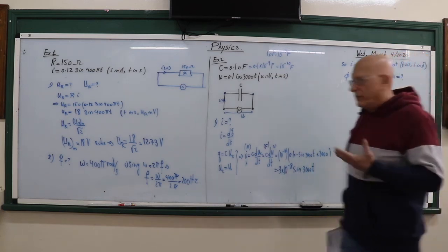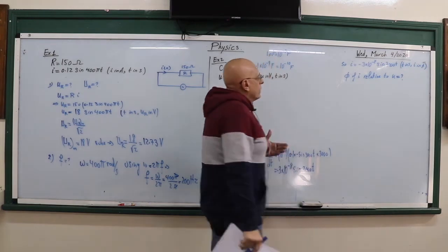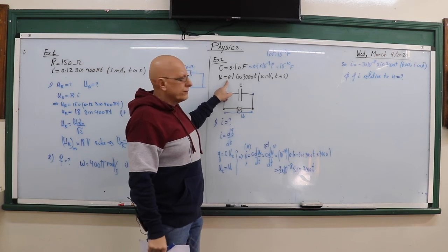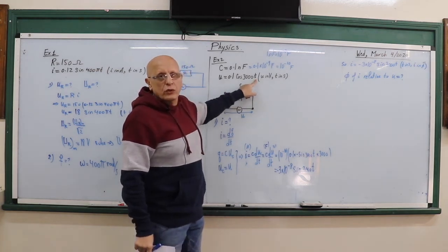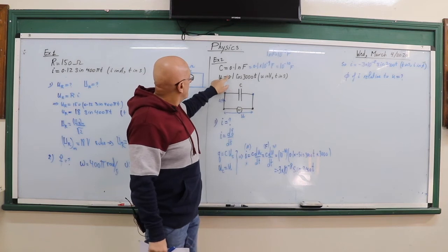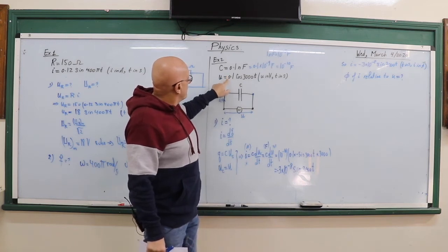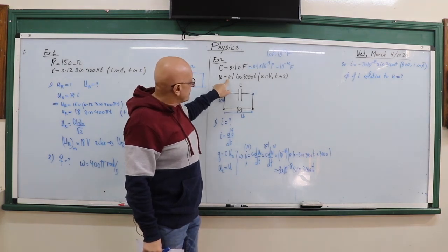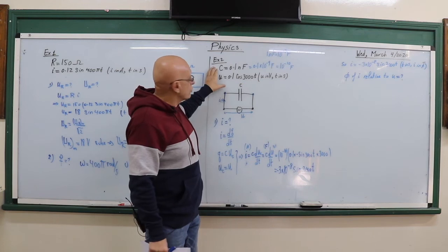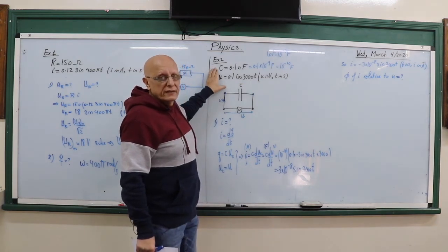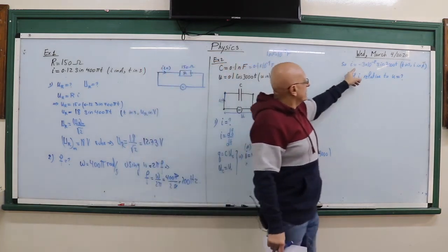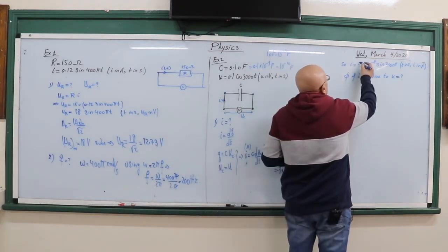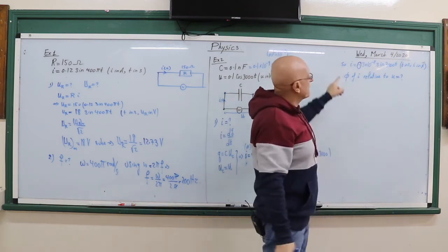Here in this problem, which is the reference? If you look at u, you will find that phi of u equals 0, and before the amplitude there is a positive sign with phi 0. This means that u is the reference. I is not the reference because the minus here corresponds to a phase difference.